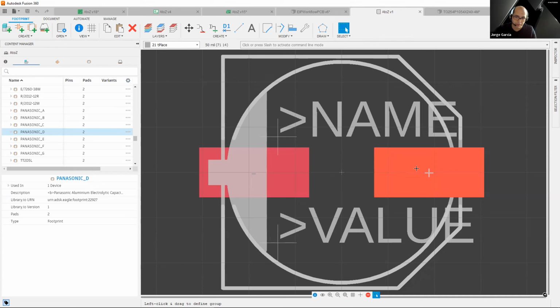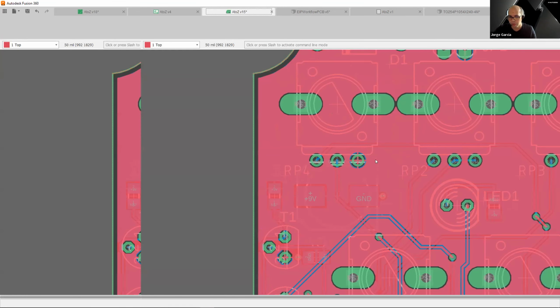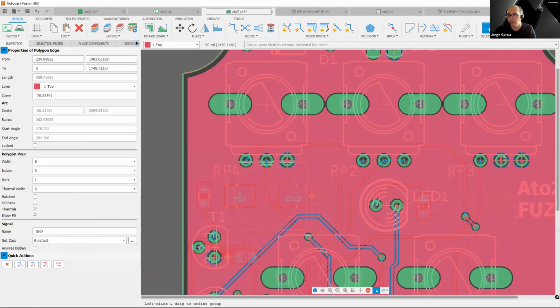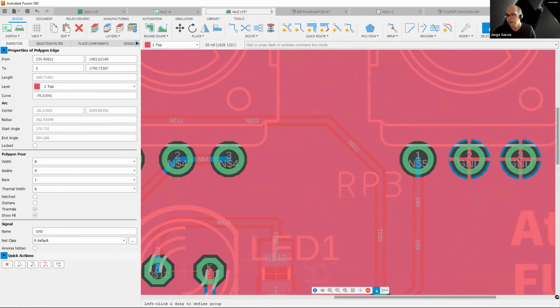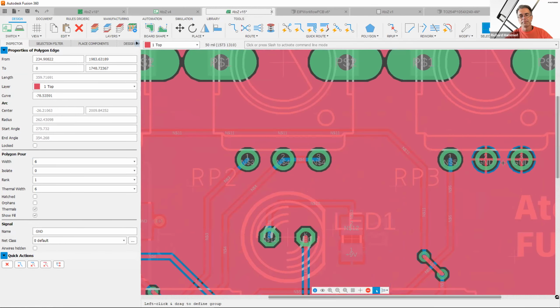If you do it in the library, the advantage you have is that in the PCB, it will swallow the pad, but everything else will have a thermal connection. So depending on the component, that can be a good option. And that's typical with high dissipation regulators and things like that, or switch mode power supplies or a power transistor. You'll just get whatever its heat dissipation tab is. You'll always uncheck thermals on it. That way, whenever you use it, you know it's just going to be a solid connection.